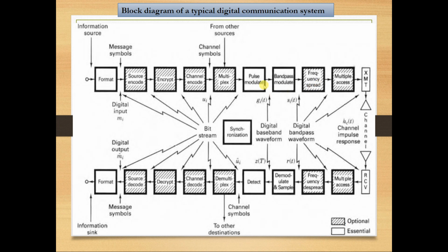According to what? To the incoming information. If the incoming information here is a rectangular pulse, let's say representing 1, then you can make the amplitude of your carrier reach plus 10 volts. If the incoming information here is, let's say, 0, you don't have information, it's a 0 bit representing a 0 rectangular signal, it means you are not transmitting anything, then in this case your carrier can be a signal of voltage equal to -5 or 0 or 1 or whatever.